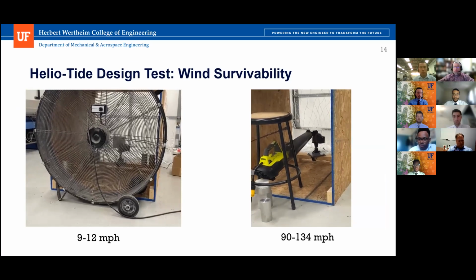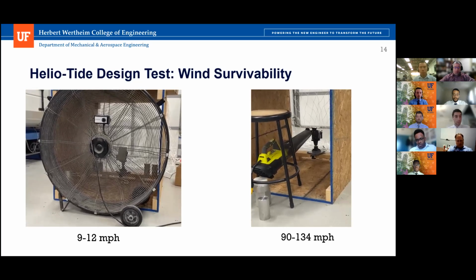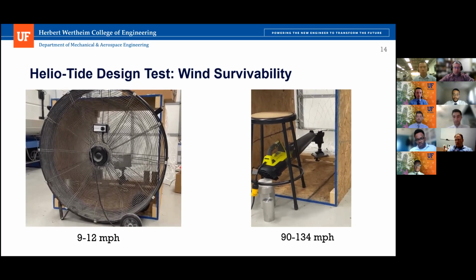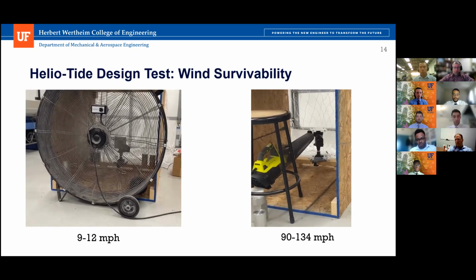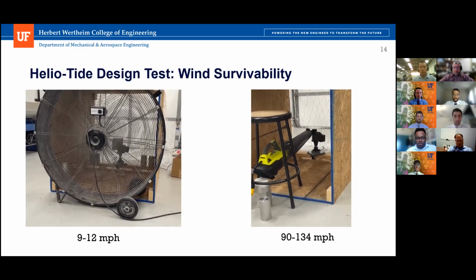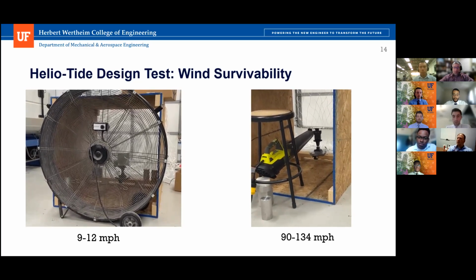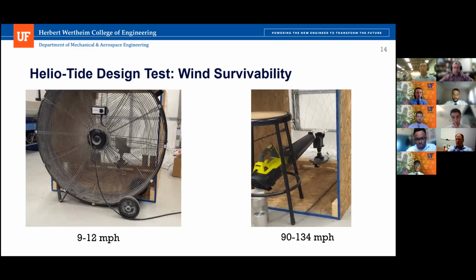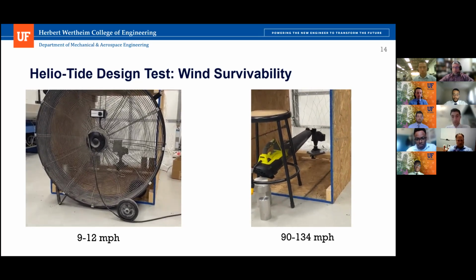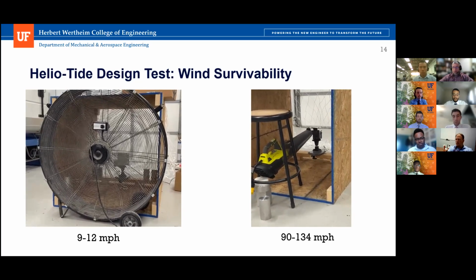In order to validate our prototype in a laboratory environment and achieve technology readiness level 4, it was subjected to a battery of tests to collect evidence that the performance requirements set forth by the customer might be attainable. The first defining test was a wind survivability test to demonstrate that our prototype, which is aerodynamically similar to our final design, can withstand the most extreme weather conditions possible at the target installation site in Las Vegas, Nevada, with a factor of safety greater than 2.